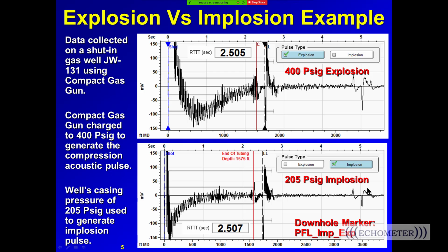So this is not only an example of direction of kick, but you can see a marker being used here in the tubing. It's been used for the distance to liquid. And you can see the idea of a repeat echo. This echo is repeated here, and the liquid level is repeated here, and the time from here to the liquid level is exactly the same as the time from the liquid level kick to the repeat of the liquid level. So the repeat's travel time is the exact same time as from the initial blast from the shot to the echo in the well. All right.